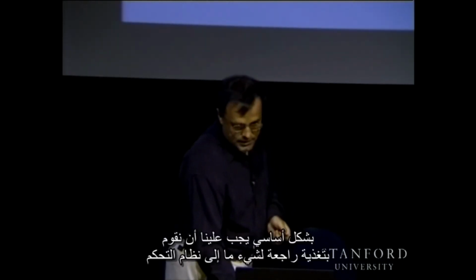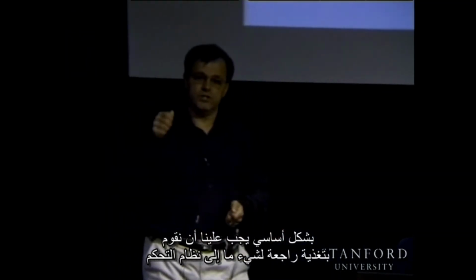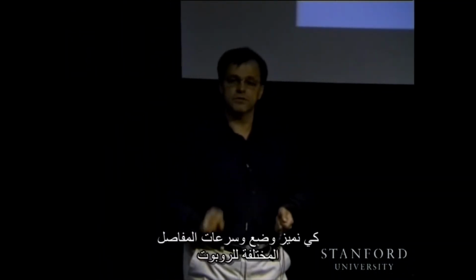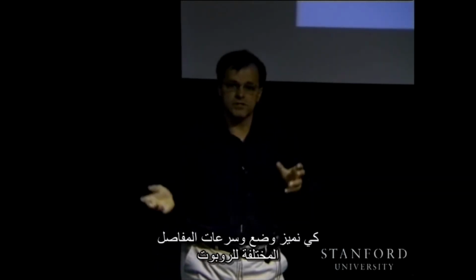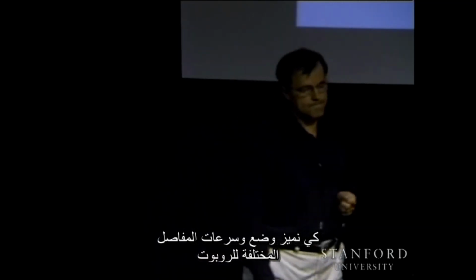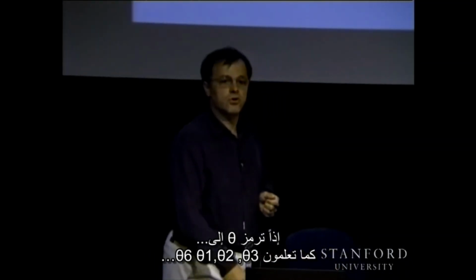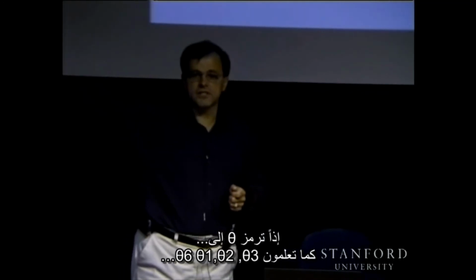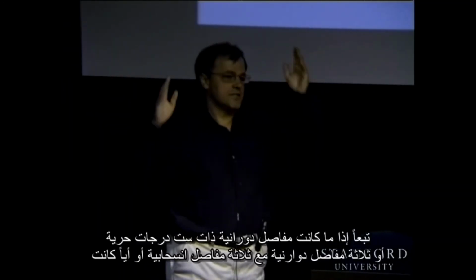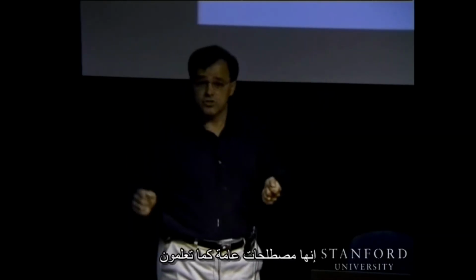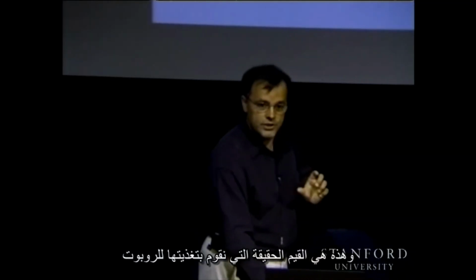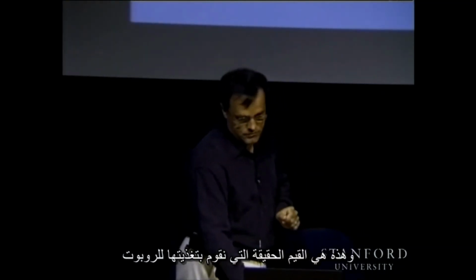So, runtime path generation. So basically, we need to feed something to the control system to tell the different joint positions, velocities, etc., for the different joints of the robot, right? So theta here stands for theta 1, theta 2, theta 3, theta 6, depending on whether it's 6 degrees of freedom revolute joints or prismatic, revolutes, whichever, it's a generic term. And those are the actual values that we feed to the robot.